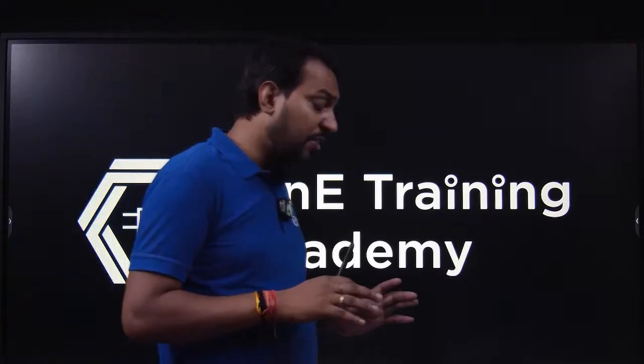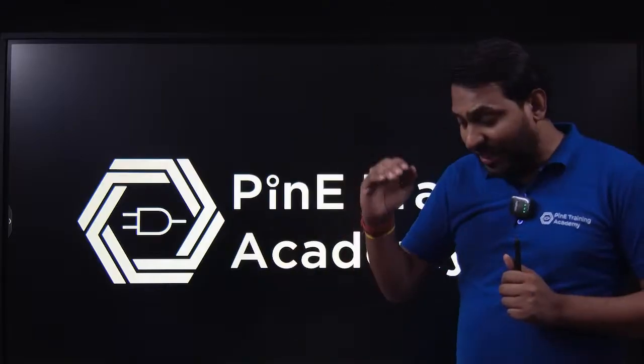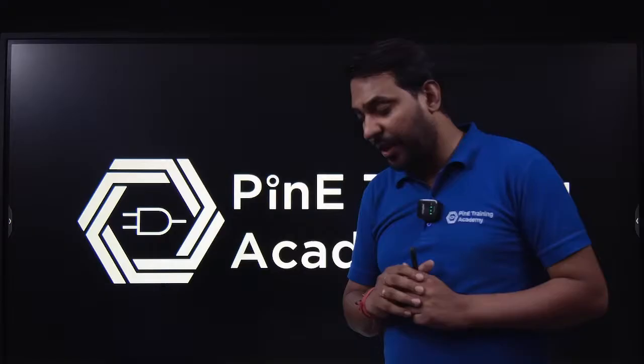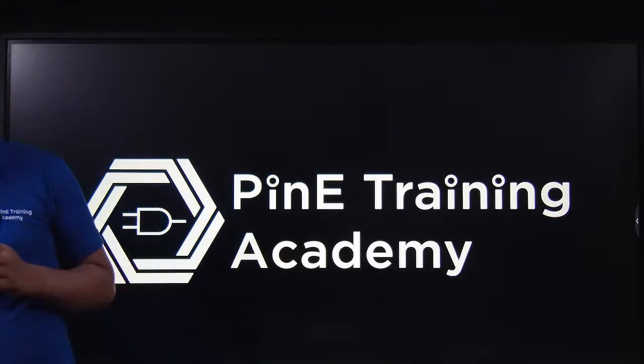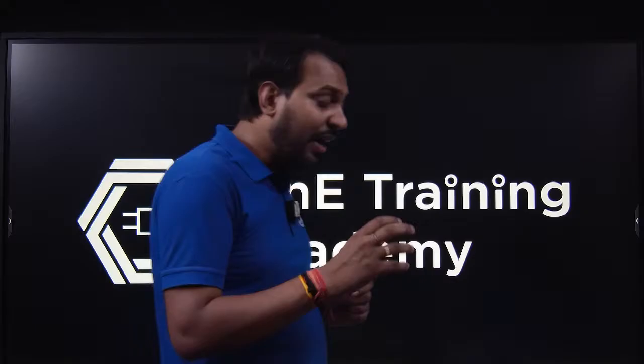After the physical verification, you are going for what? That is extraction. If you extract your layout, you get the parasitics, that is resistor and capacitor. Of course, MOSFET has CGS, CGD, CDS, CGB. Okay, they have a lot of capacitance.